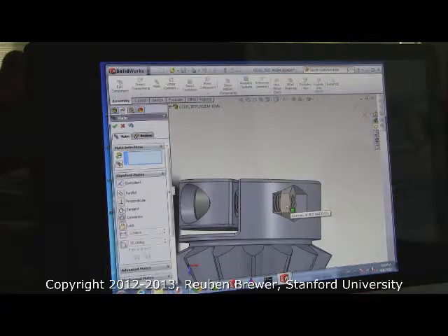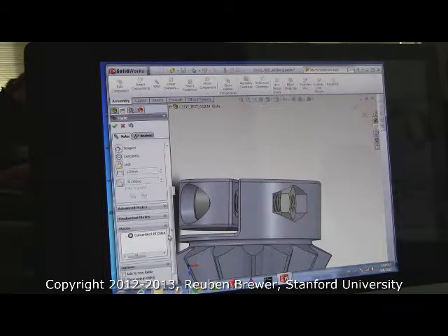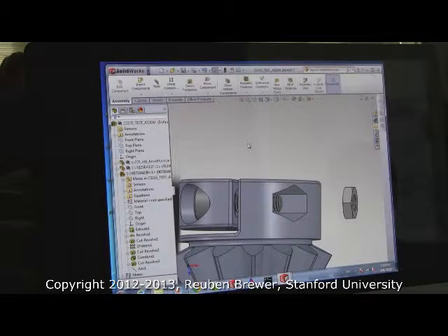Okay, now press, nope. What if it's going on the other end of the screw? That's okay. We're going to take care of that. What if it's kind of in the middle of them? Totally fine. Take that nut and drag it around. Until we've constrained something about a direction, we are free to move it. Now the one note I will give you is you can't have anything selected when you're doing that.